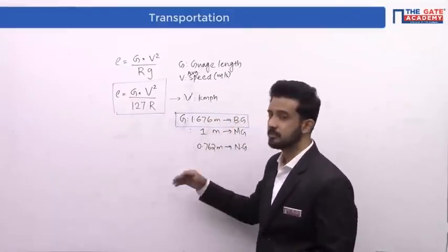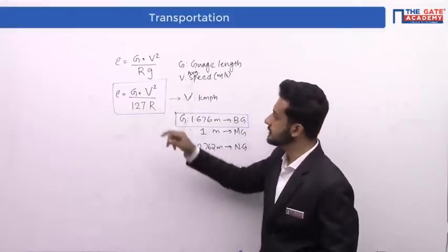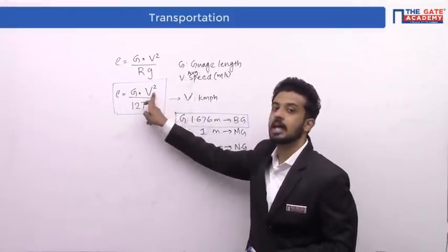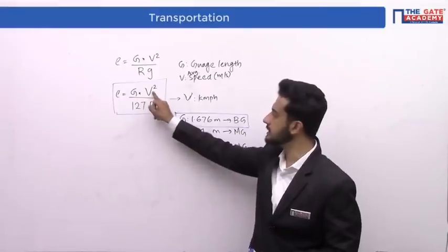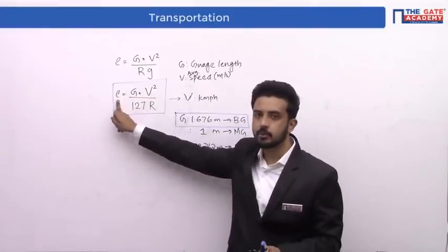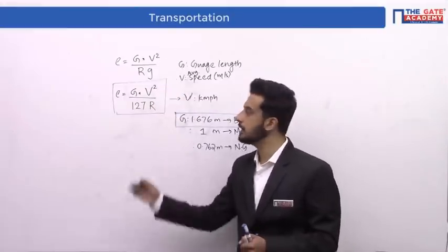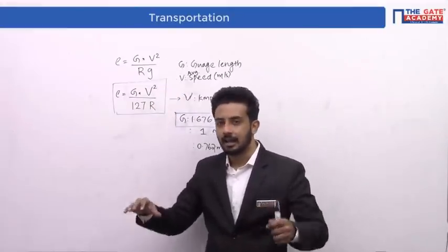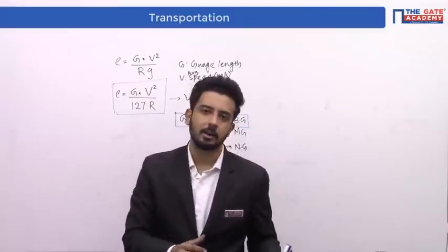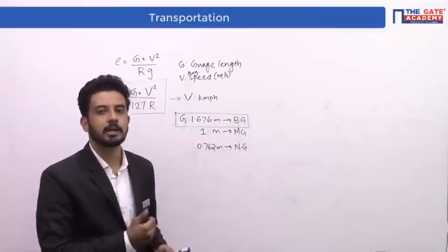But for some fast moving trains, this V is average speed. Based on this average only we are giving super elevation, and for some higher speed trains they are actually getting less super elevation compared to what is required by them.